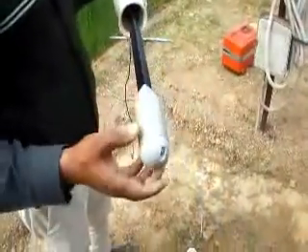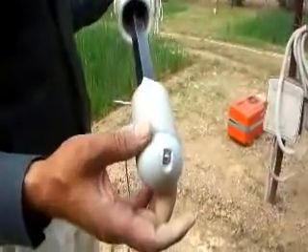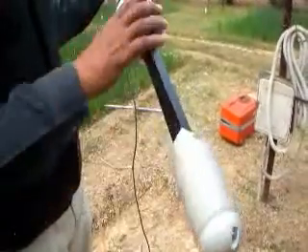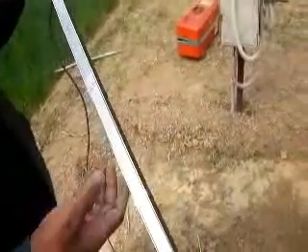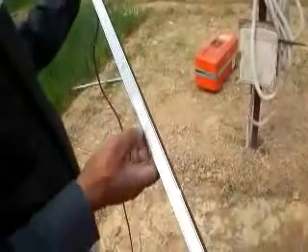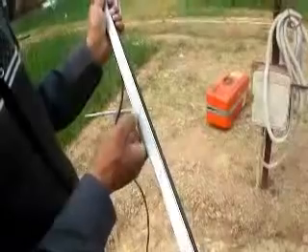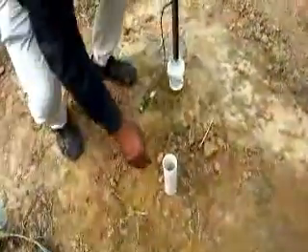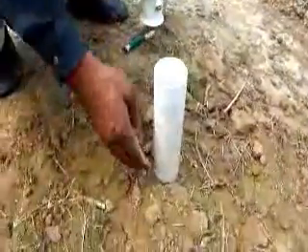So this is FDR. We have a bulb which has a dimension of about 5 centimeter, and it has a scale. Once it's a closed arrangement, it has a scale to go inside the access tube for 10 centimeter, 20 centimeter, 30 centimeter, 40 centimeter, 50 centimeter. We have to correct this scale with respect to this tube which is over this soil surface. So let us measure this.